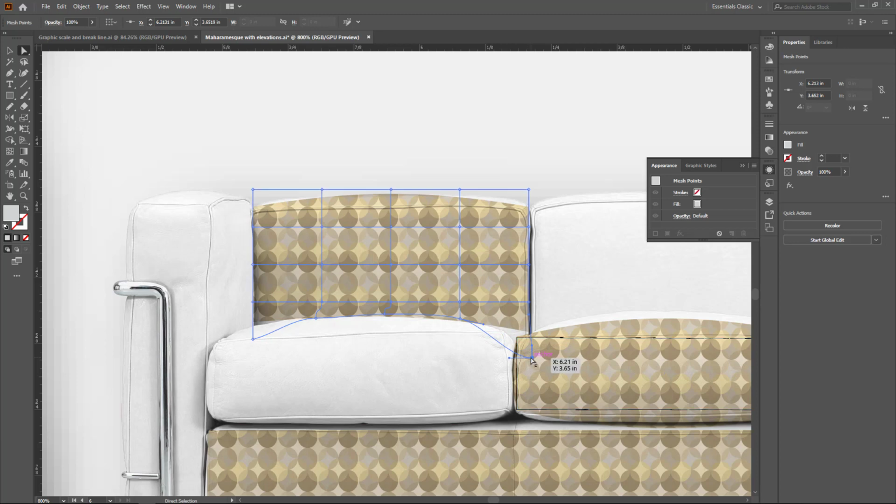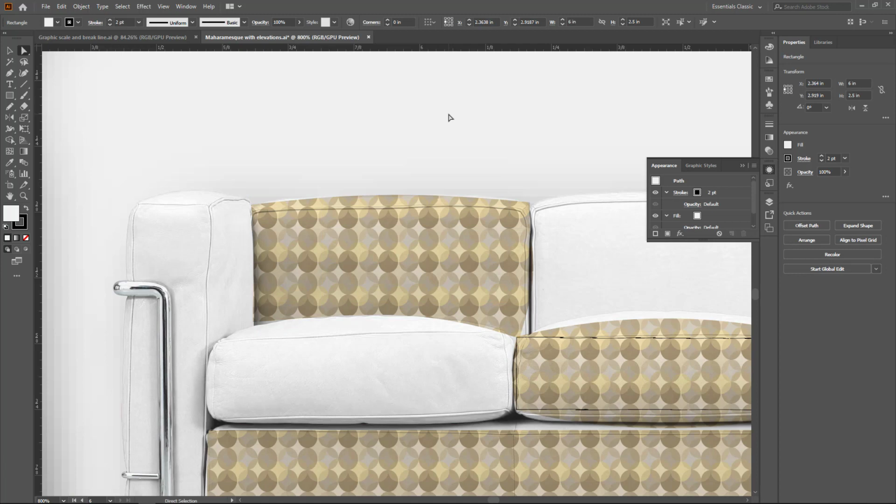You can even change these Bezier adaptation points here to modify and hug that curve pretty tightly. I can drag this down a little bit, but maybe I'll drag this up a little bit just to get those corners. And this is a way you can subtly modify the geometry of these objects. Again, not perfect. You can spend a lot of time making it perfect, but that's pretty darn close.